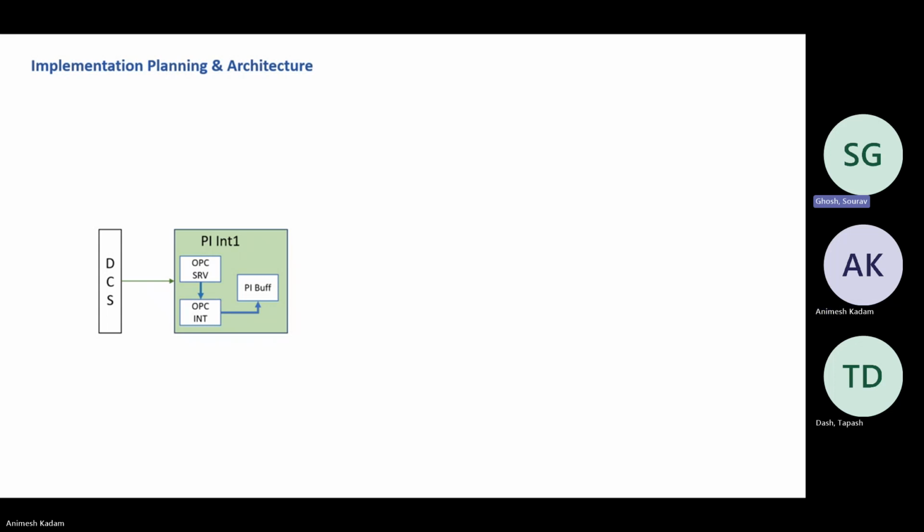Let's suppose I have different OPC servers for different PLCs, and they are on different machines. Now I have only one Pi node. In that Pi node, I am trying to get all 4 instances, for those OPC servers, in the same Pi node. So in that case, will the DCOM setting be the same or different?